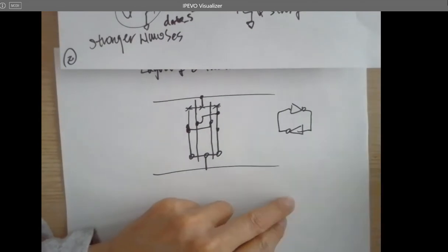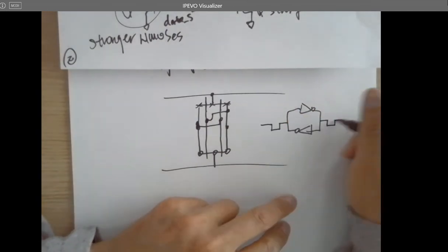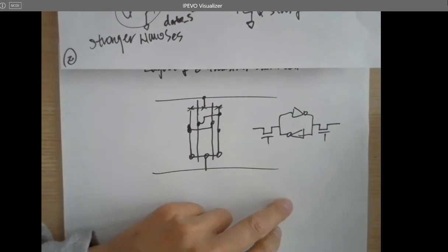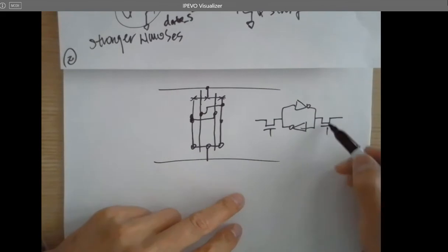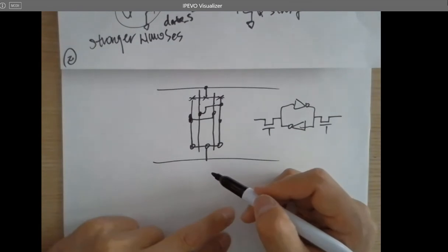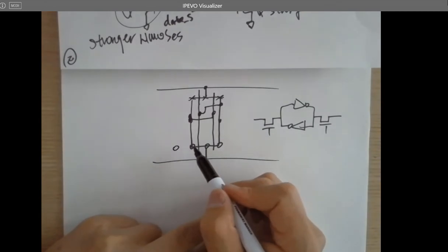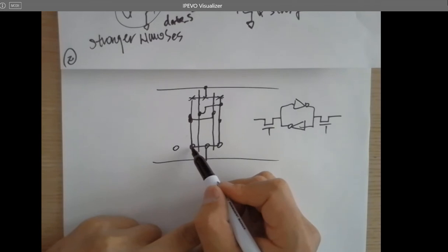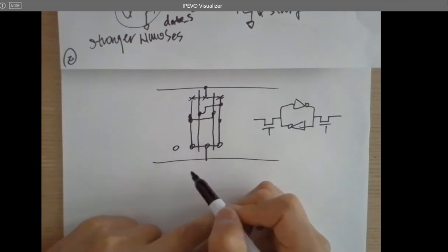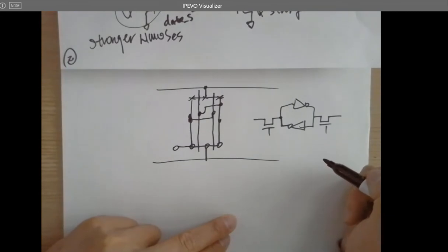And this is done. Right, and also we need this to form the 6 transistor SRAM cell. And these are two NMOSes, so these two NMOSes should be drawn here in this area. And so if I let the drain of this NMOS share with the drain of this NMOS, will that work? I think so, because the output is being directly shorted to the drain. Right?